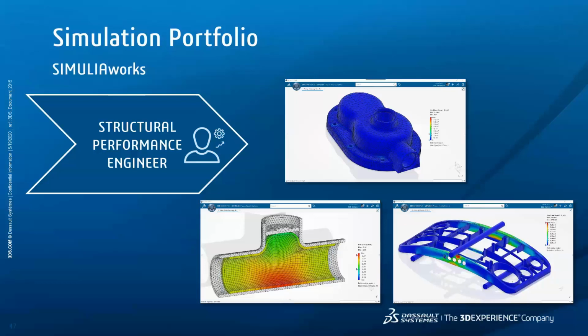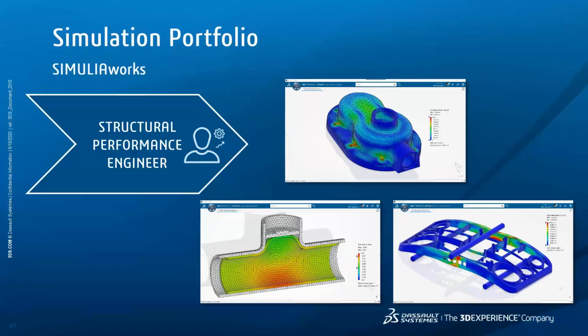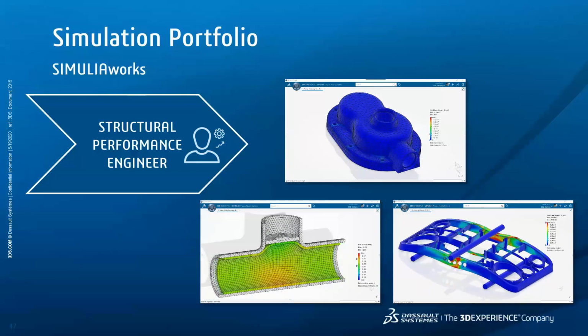In order to ensure beginners can understand the tools, there's a guided workflow that details what the different tools are, what they do, and whether or not they're required for the simulation in question. Meshing takes a beginner to expert approach, only requiring the user to delve down to the controls based on their experience. The default recommendations will suffice. In terms of post-processing, you can interrogate contour plots and create history plots, and you can look at key locations using sensors. There are also other tools available, such as creating reports based on templates.